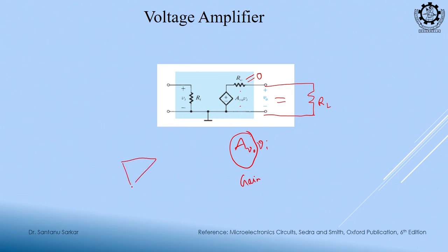Okay, let us come to an op amp. You have studied op amp, right. Can you tell me the ideal characteristics of an op amp? Voltage gain AV infinite, input impedance Ri infinite, output impedance R0 zero. Can you understand now why it is 0? This symbol is nothing but an op amp symbol, a voltage amplifier. Now, what should this Ri ideally be? Now, let us add one voltage source here.